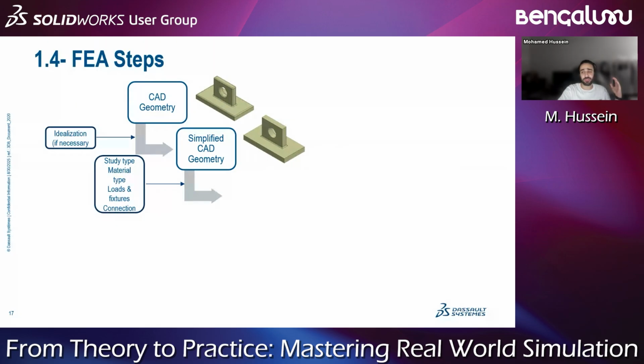You need to define your study type, the material that you are using for constructing this part, the loads that are affecting the part, and where it will be fixed, or the type of fixation that you are using, whether it's welded to any wall or ground, or what the fixation type will be.